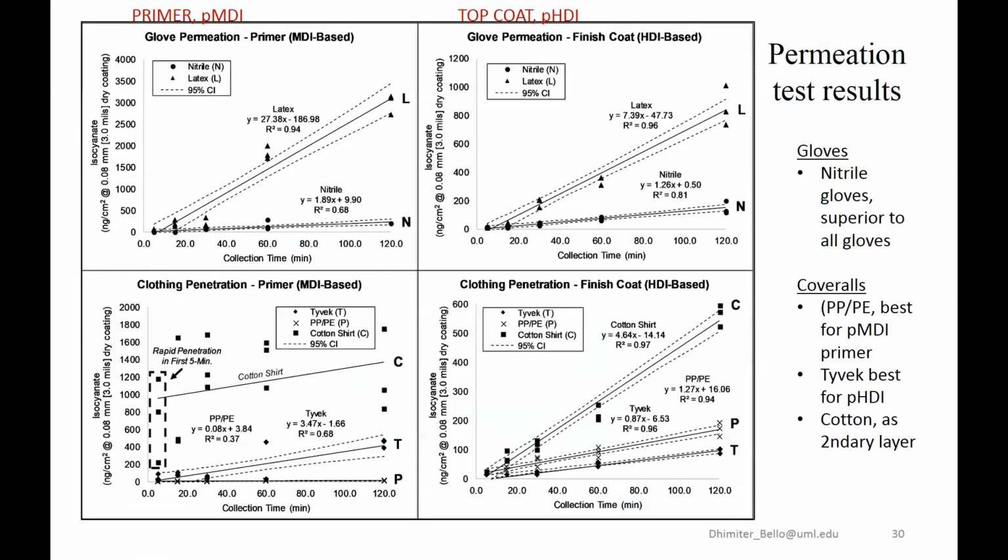And so the experiment was to spray a fixed amount, relatively reproducible, and then collect on a filter on the back of the fabric at different time points, and then calculate a permeation rate. Penetration, which is the free movement of paint across holes, would be assessed based on some dyes that we use for that purpose, and that is immediate.